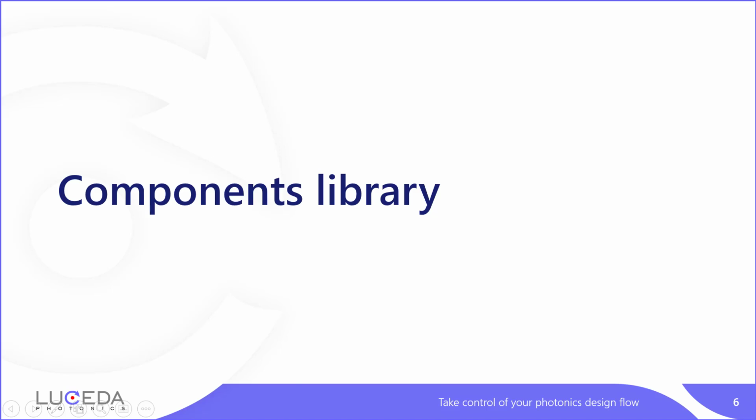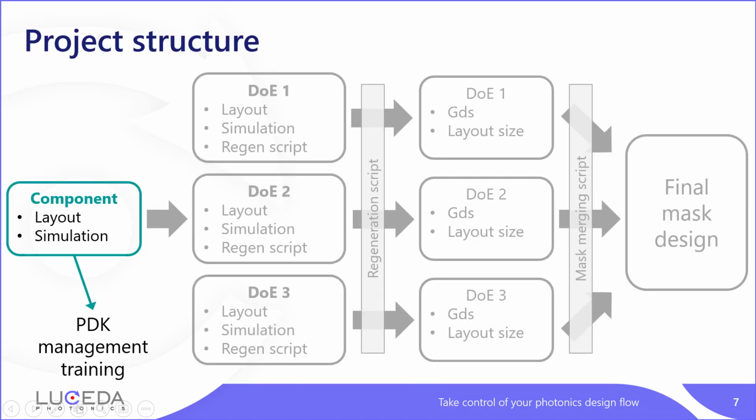So let's first take a look at the components library. Each designer is going to contribute their component design into the PDK. So already here, we need to implement good practice on how the PDK is going to be organized. For this, we have a separate training topic on PDK management. At Luceda, we recommend a certain PDK organization structure that every team could follow in order to reach a good design organization and also to facilitate the entire PDK-based design workflow.